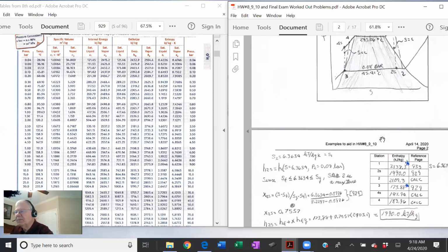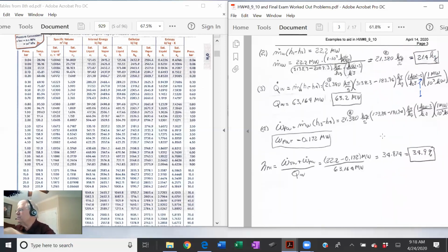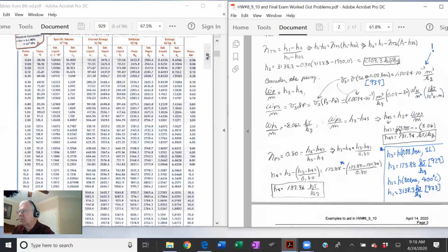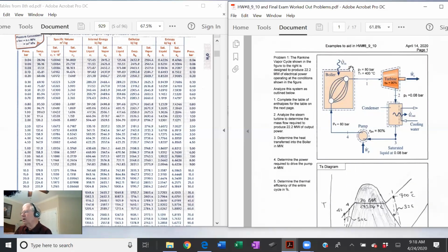The interesting thing about it, we got a decent thermal efficiency of 35%. Pretty decent number. It's a good number, actually. Now, just because that looks fairly low compared to some isentropic efficiencies, that doesn't mean that's not a very economically viable process, because what you're doing is putting pretty low, inexpensive heat into a boiler, and you're getting about 35% of the heat in out as good quality shaft work.